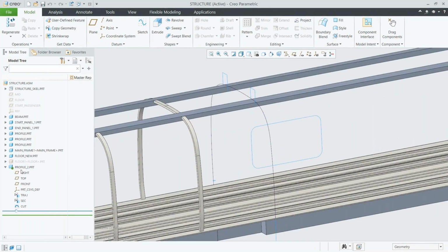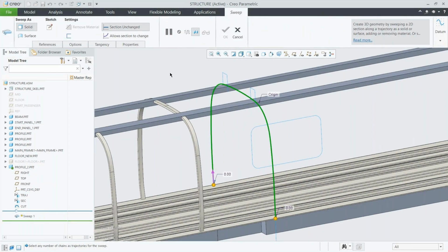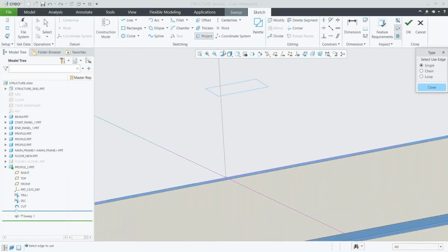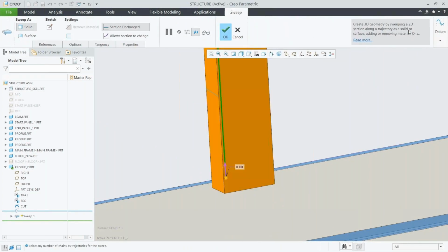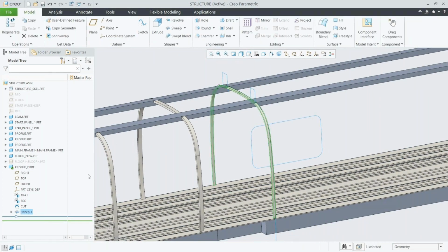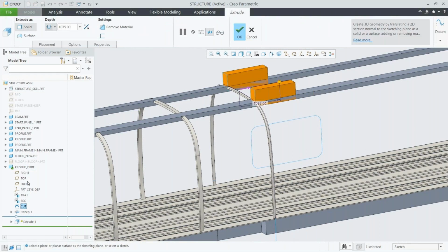Now, when you go to work with that, you'll see here in the structural assembly those pieces of geometry pop up just like they were made in this assembly. This arch is from that top level, and now you can build the parts from the structure that you need. So whoever's working in the structural assembly can make the arch right from that line. No need to do anything differently.